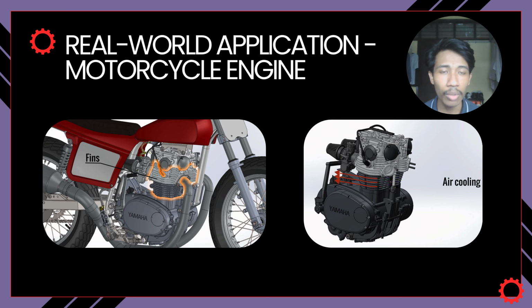Now let us trace the complete heat transfer path. First, fuel combustion inside the cylinder produces extremely high temperature. Second, heat conducts through the cylinder wall to the base of the fins. Third, heat conducts along each fin from the base toward the tips. Finally, heat is convected from the fin surface to the passing air, which carries the heat away. This is exactly the process modeled by the fin equation we derived earlier, where the fin increases surface area to maximize heat transfer to the surrounding air.